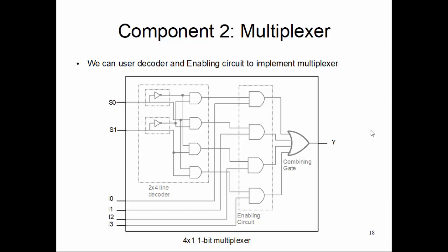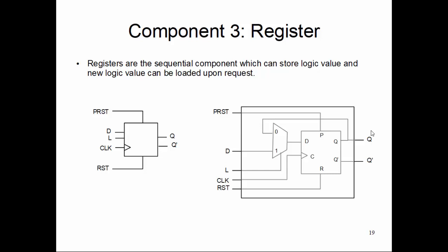Now the third component, which is a register, let's talk about this. This is used as a 1-bit storage element. Probably you remember we constructed a flip-flop in the previous one or two lectures. We built up a flip-flop, and you may ask, hey, a flip-flop stores a bit, right? What needs to be done on top of that?